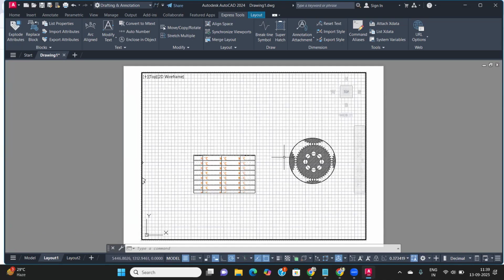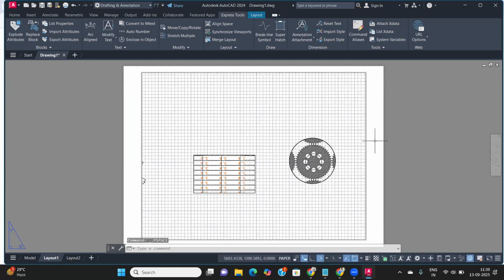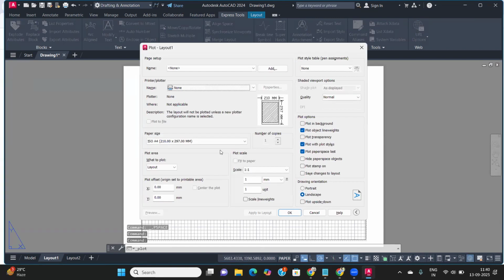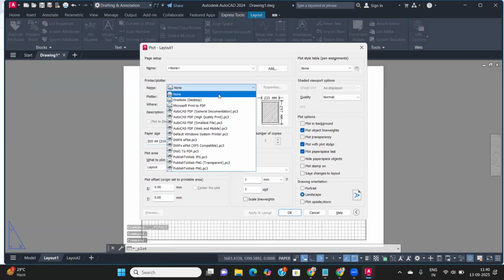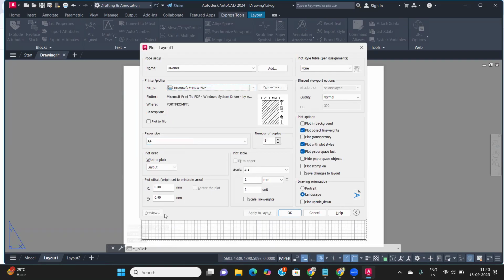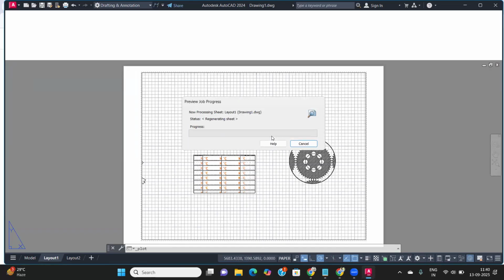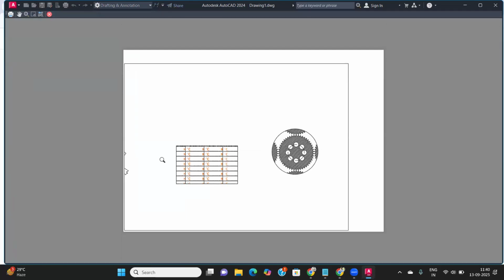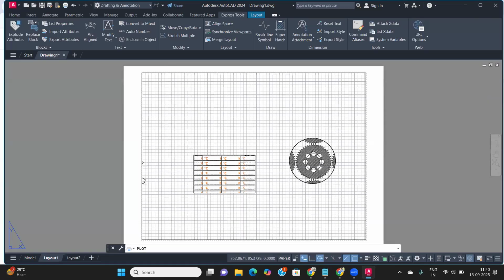I just click, and then also you can adjust it, and outside we double click on this part and it will be shown. Okay, and then if you press Control P and then select your preview. Okay, I select first where we want to show, then the preview option will be shown here. Okay. Select the preview, and this will be shown. Okay, this part will be shown. Okay. This is the way you can create your plots by using layouts also.